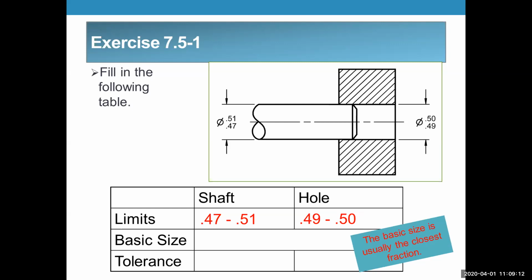standard doesn't do that, because, I think, they feel like it might be too confusing to some people. If you've got shafts and holes in the same drawing, and you've got them dimensioned that particular way, I can tell you from experience that I've dimensioned it that way, where I've kept the maximum material on top, and no one's ever had an issue with it. As a matter of fact, I've had machinists tell me that they prefer it that way because, like I said, when you look at either one of these dimensions, the first number you see is the top number. So I prefer it that way.